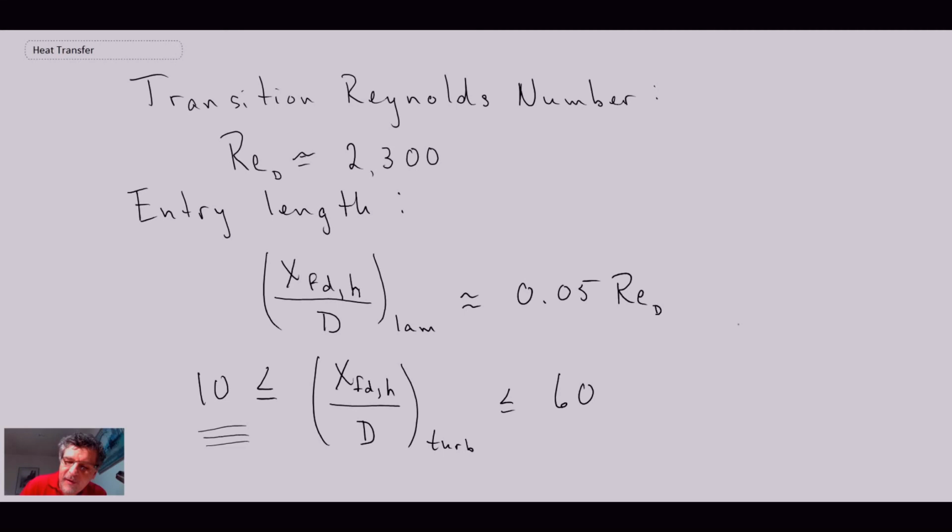There you might have something where you have pipe flow coming along and then you have an elbow. You want to make sure that you go at least 10 diameters before you would put any kind of flow metering device in order to measure what the flow rate would be in that pipe. So anyways, that's just how to get to the fully developed flow regime. And here the elbow would be a thing causing an instability that changes the flow field. And so it takes a while for the effects of the elbow to wash out.